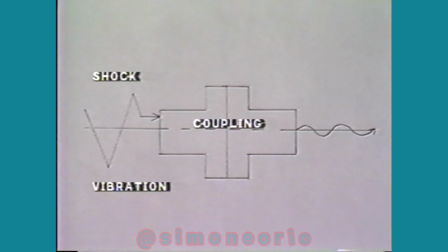Shock and vibration may be passed from one machine to the other. These are destructive elements, putting stress on mechanical components. A flexible coupling, which has the ability to dampen shock and vibration, helps protect equipment.